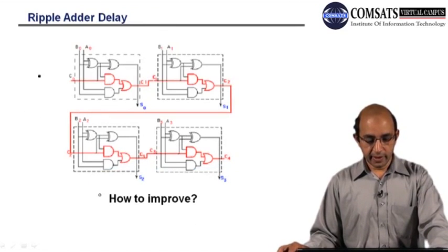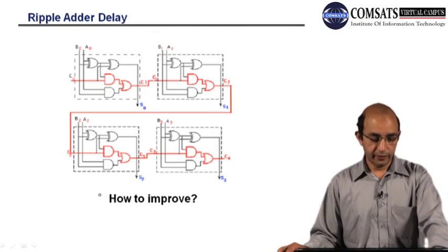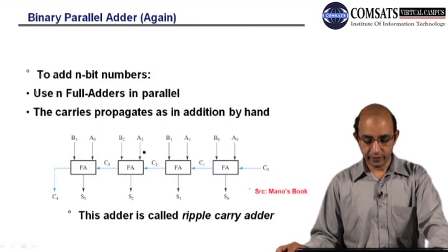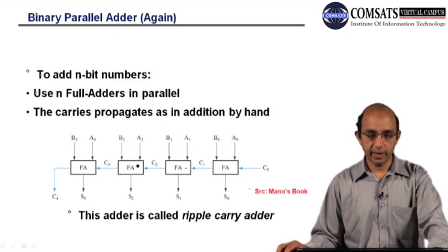Okay, and then there is another problem, right. If I go back, we know that each gate introduces some propagation delay, right. If this has some amount of propagation delay, then that delay has to be moved here, right, and then that delay will keep on adding up till we have reached here, right.